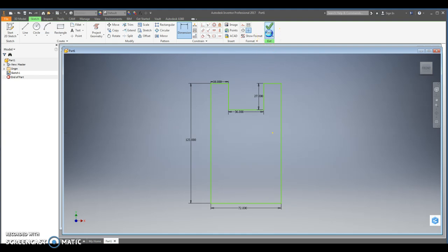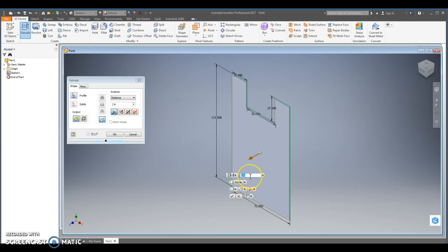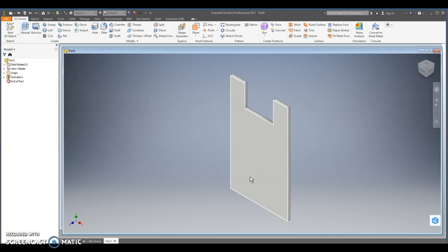I'm going to go ahead and hit Finish Sketch, and then hit my little house here in the corner. We need this to pop out. So if you remember, the command was extrude, and we need this climbing wall to pop out 3 inches. And there we have our wall. But if you look at your blueprints, we also see that there are some holes on that wall. So we need to be able to make holes so kids can climb up it.